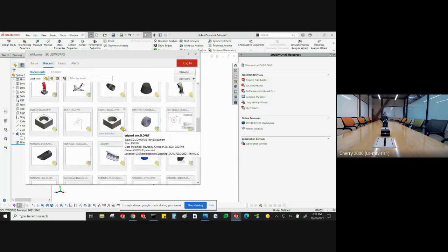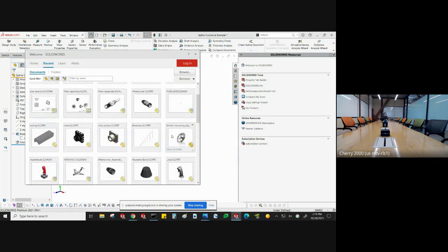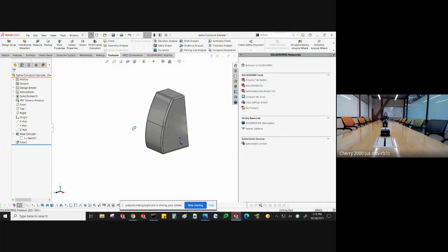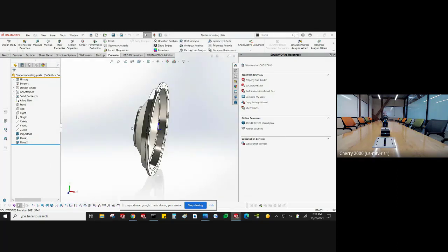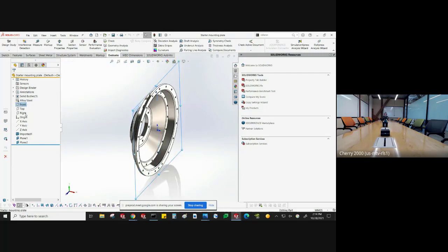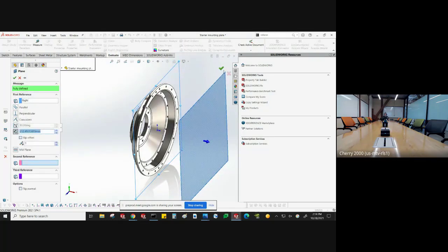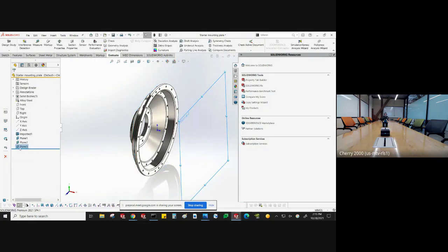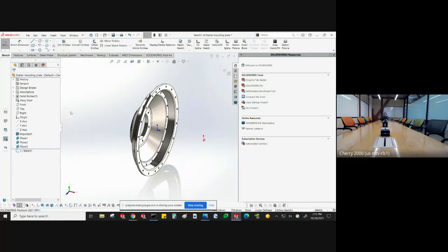There's also another tool inside the sketcher that is really nice. You heard me talk earlier about top-down design and envelopes and doing convert entities, where you're basically grabbing edges from geometry and putting it into a sketch, which is not new. We've been able to do that for a long time. So let me just open a sketch on this plane over here. Go to my convert entities.